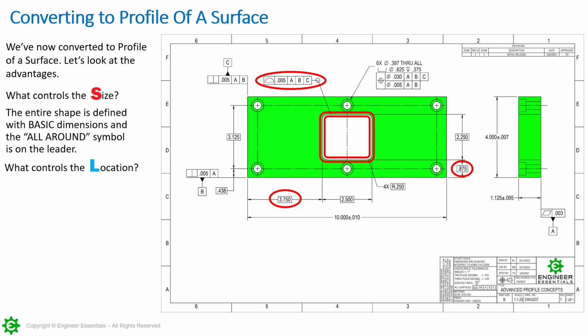The 7/8 over here, the 0.875, that one's coming from B. The 3 3/4, that one's coming from C. But they're coming from datums now, and they're locating the tolerance zones. Very important to understand with GD&T, it's all about tolerance zones. So we didn't have all of these tolerance zones with coordinate dimensioning that were all tied together and locked together, but they are now. And whether you know this or not, this makes it more simple.